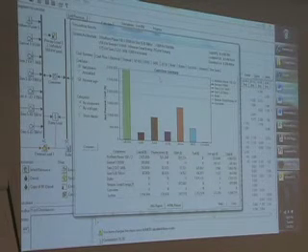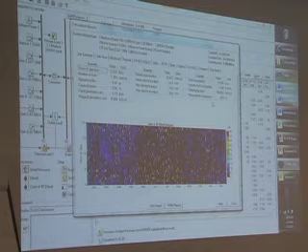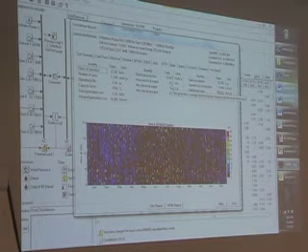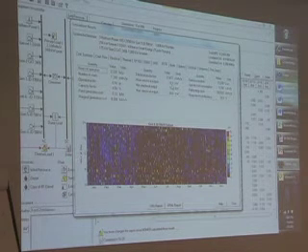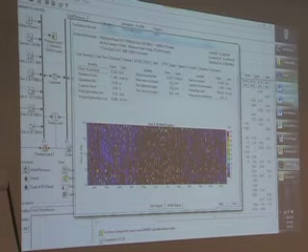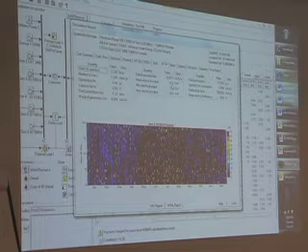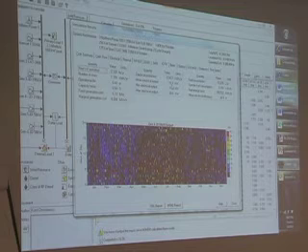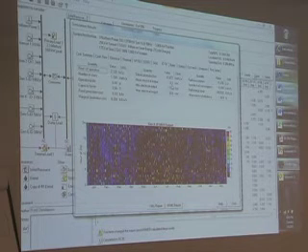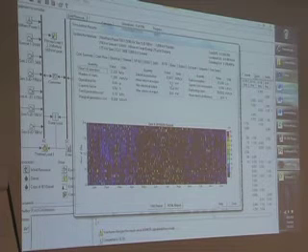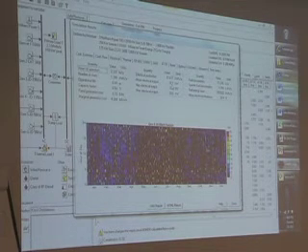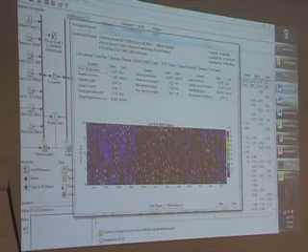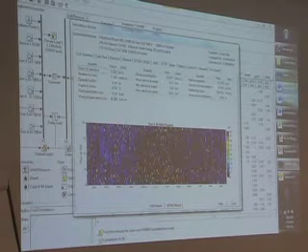And so it's all a bunch of trade-offs. So here it's gone down even more. So it's bad for the diesel, but it's better for other parts of the system. How do those two trade off? Well, sometimes it'll trade off one way and sometimes it'll trade off another way. It's not clear without doing the modeling that in this case, what you're saving from needing fewer flywheels more than compensates for the reduced efficiency on the diesel, assuming that 80% operating reserve is adequate.